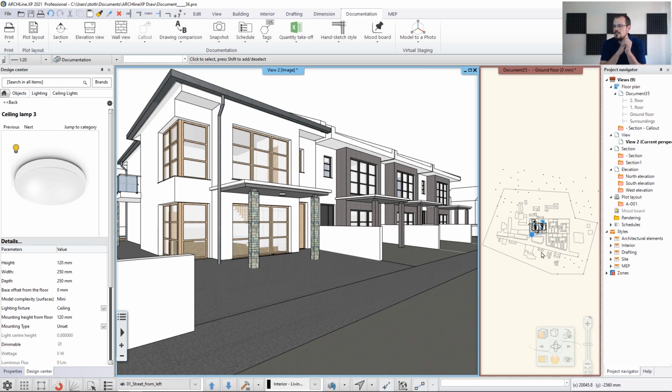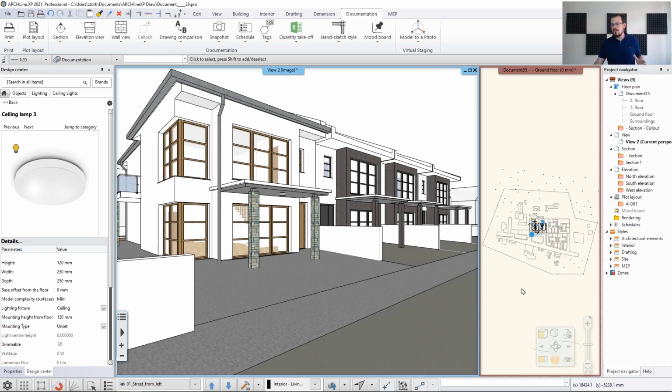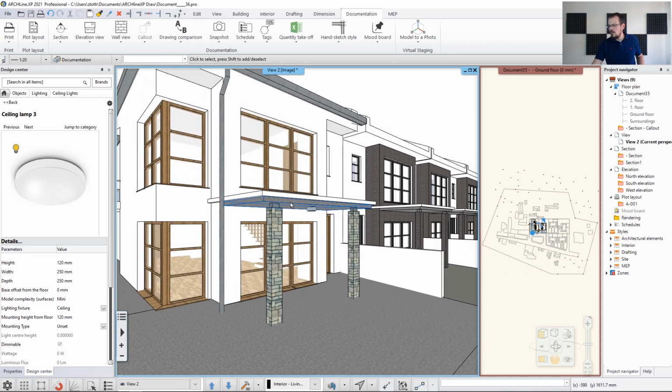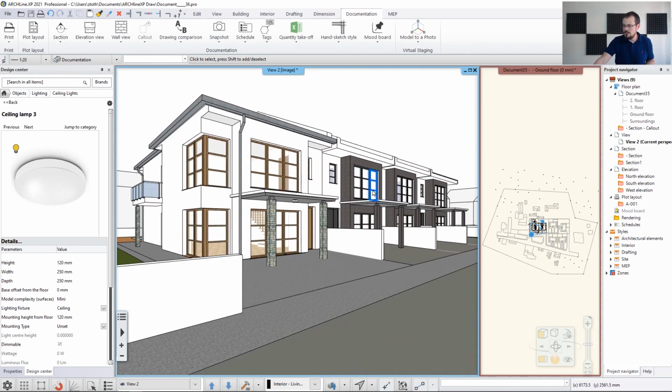One thing you need to know is that the realistic representation, for example, is a bit of a tricky thing because it tries to replicate the effect that things which have the same color might not look the same in different circumstances. For example, if you have this grayish texture applied to the underside of a slab, it might look a bit darker than it actually is. So if you want to make sure that your clients understand how the colors actually look, or how they are actually behaving, then you might need to go with the consistent color option, which is what I use all the time. So in this scenario, no matter how the model is portrayed or moved, the colors always look the same. So that's one trick that I always use.